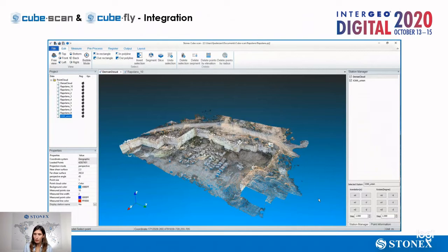And so create models with different sensors. Maybe it's easier with a UAV drone to capture the elements of your field, but for a case like this in the image where there is a quarry, the facade of the quarry can be scanned by a tripod laser scanner. That integration allows to increase the quality of your final survey.